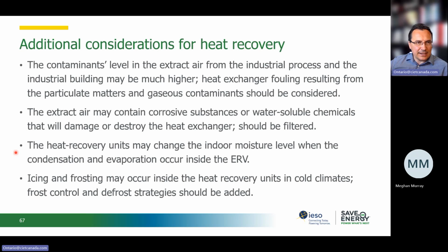So heat recovery units may change the indoor moisture level if condensation happens. We're talking about the ERVs, the energy recovery units, because they have both latent and sensible. But with that water condensing, we can also deal with icing or frosting that can happen on a heat recovery unit.